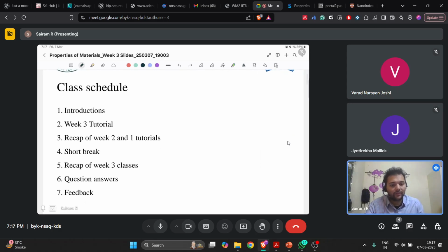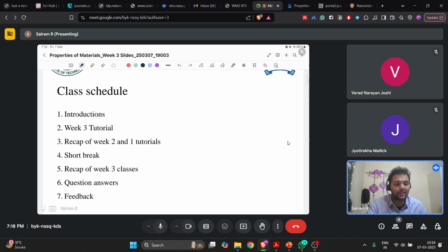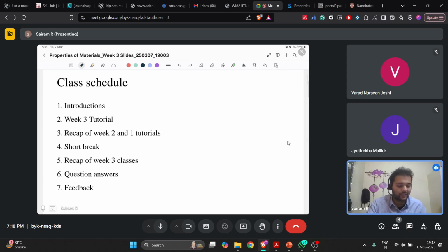Also, once we've learned in depth about the elastic modulus, we went into the nature of anelasticity, how it comes about, the concepts of relaxation time that bring about the property of anelasticity, and also what the effects of anelasticity are, which include, say, damping capacity, and other such factors.